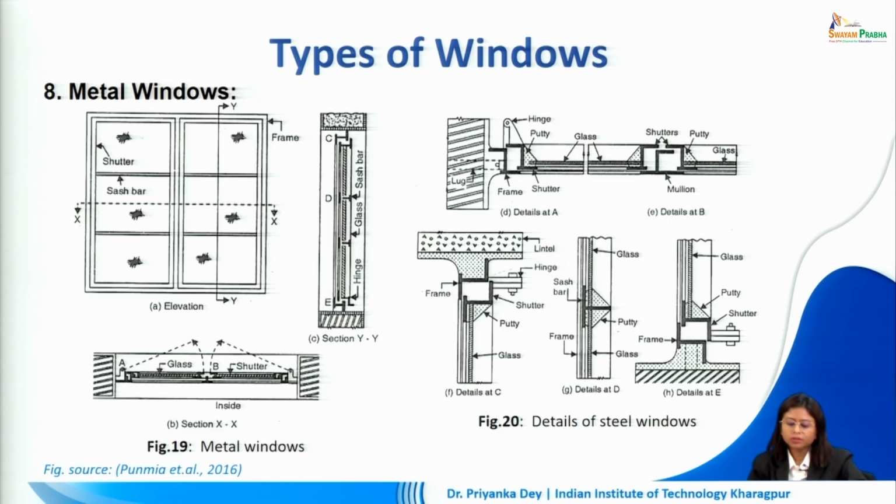So this is how different metal members can be used to create windows. They may be glazed. We also might have some portions which are opaque, but popularly glazing is done in most of these panels. We can fix the position of the glass with the help of putty, like so. There are some cases, for example, in aluminium option, we can also use beads which are available to fix the glass in its position.